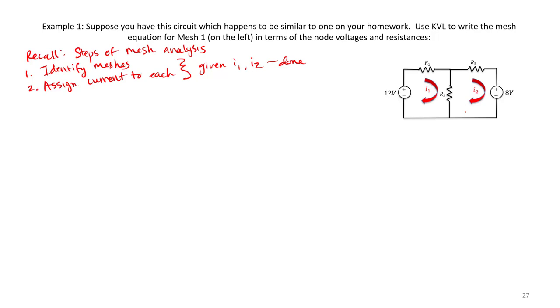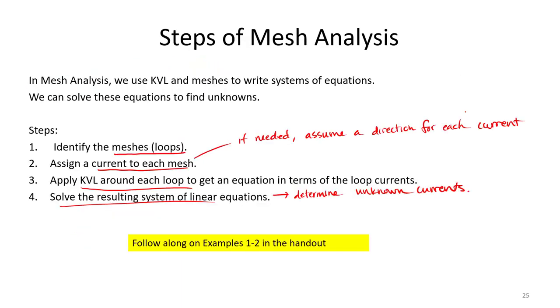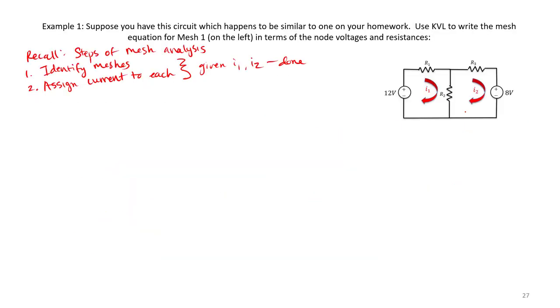You'll see that even if you happen to assume the opposite direction as I did, you would still end up getting the same result if you followed a consistent sign convention. Next step is to apply Kirchhoff's voltage law, and then write that equation in terms of currents.